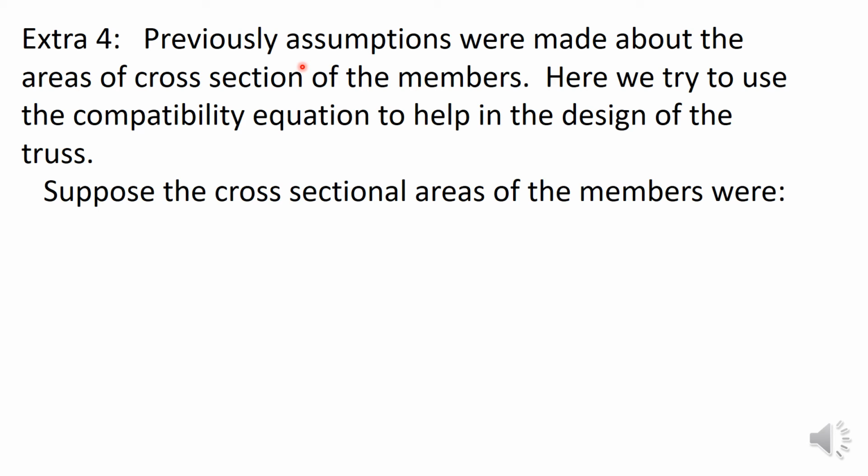cross-sectional properties. Now, if you change the cross-sectional properties of the members, then you have to go and analyze the structure again, and with the new cross-sectional areas, the forces may change, and then you have to go back and check for those new forces and redesign possibly and repeat the process.